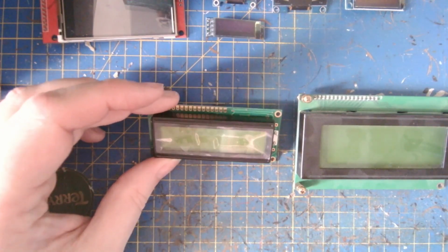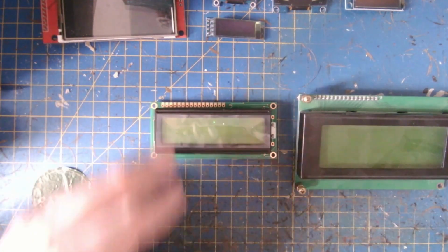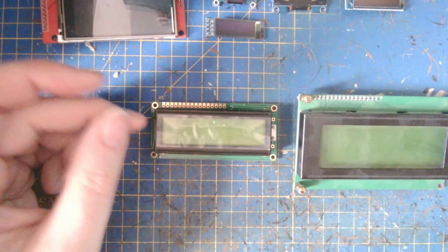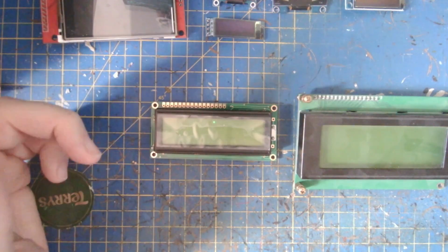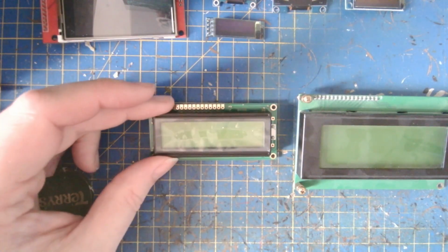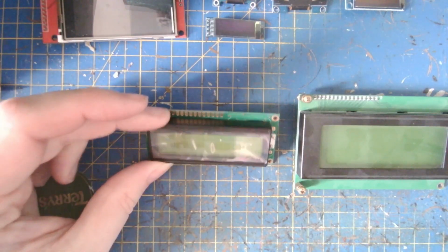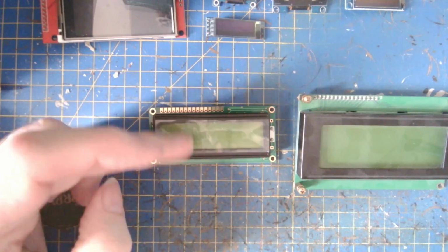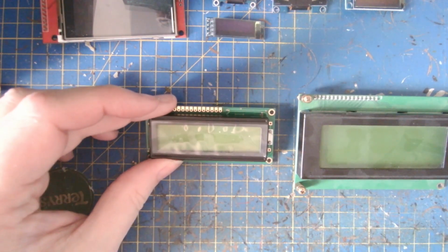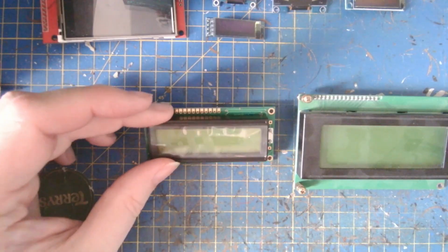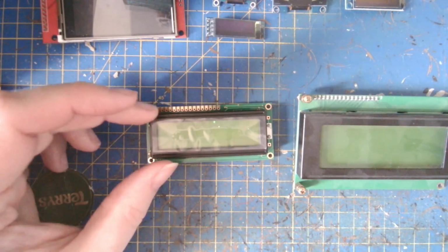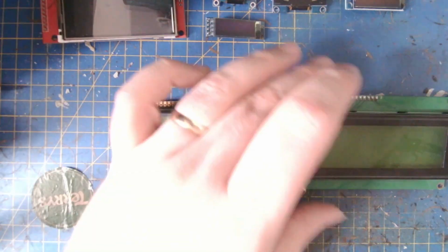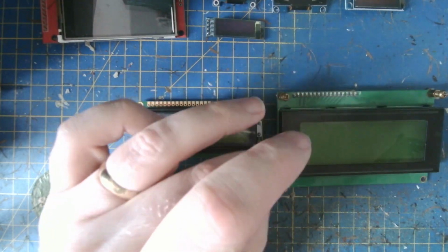Again, these two have an LED backlight. Most of them do. These ones you can see without turning the backlight on. You can also get ones that are blue with white characters, and there's some other colours. The main feature here is the liquid crystal display itself is see-through, and it can be energized to fill in little squares in black in this case. These have a character interface, so these have a grid of 8 by 5 pixels. This smaller one is 16 characters along and 2 rows. The bigger one here is 20 characters along and 4 rows.